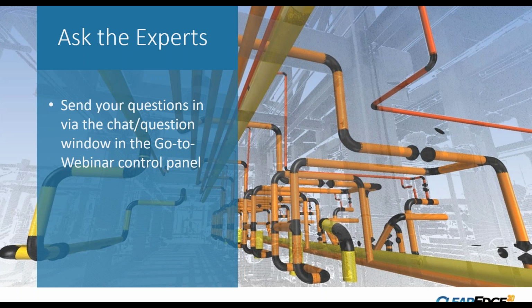Got it. Two more questions. Can you adjust tolerances by level and by element? Yes. So the answer is yes. Generally speaking, we would recommend that you treat any bulk group of objects that you want to have a different tolerance as a different analysis. So, for Tim's example, you might run level 1 as one analysis, level 2 as the next analysis, and level 3 as another analysis if you had a different tolerance, because steel, as it goes up, you may need to make adjustments. The other thing to do is to break up those scans and have localized control.